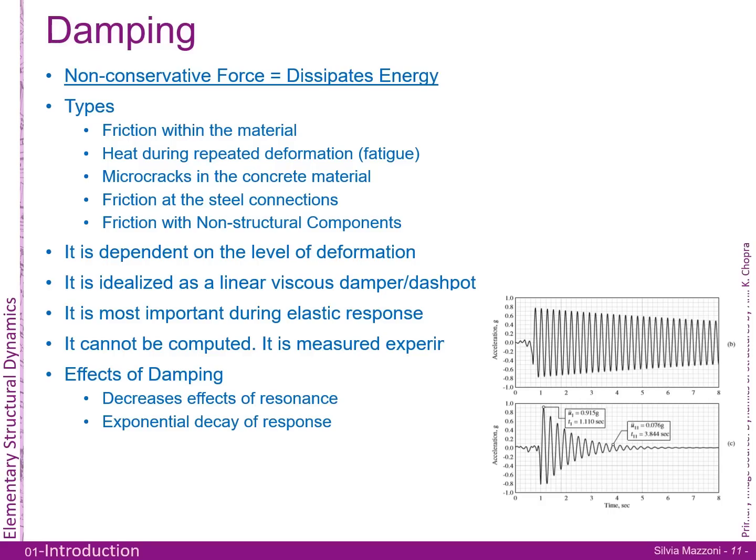And it also does, as I said, an exponential decay of your response. Here are two figures on the right. This is a slightly damped system, so the response takes a long time to die out, while a highly damped system reduces in response a lot faster. And in the end, this is really how we measure damping, from these plots here through experimental testing.